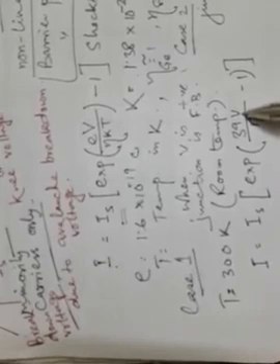Now here the voltage V is nothing but the voltage drop across the junction of the diode, and this is nearly equal to the voltage applied to the diode, because the bulk resistance inside the diode, meaning the resistance of the p-type semiconductor and the resistance of the n-type semiconductor taken together, is called the bulk resistance of the diode. During the forward bias, that resistance is very less, and that's why the diode will conduct heavily.